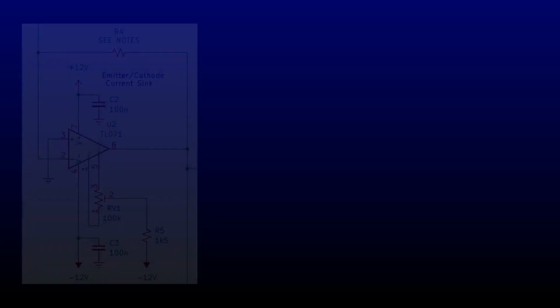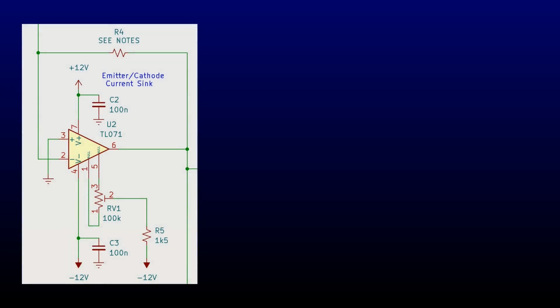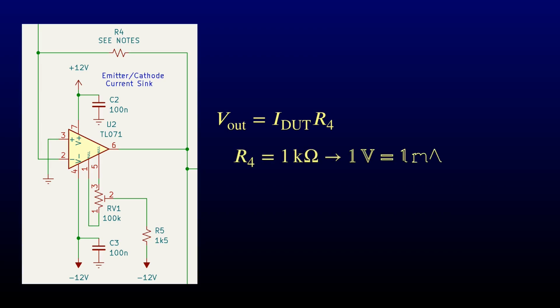In the initial design, I made the current measuring circuit look like this. For R4, I put a collection of resistors side by side on the breadboard, with values 1K, 10K, 100K, 1 meg, and 10 meg. Those let me select the scale for reading out the current as a voltage. If I assume a 10-volt full-scale output signal, I get full-scale ranges from 1 microamp to 10 milliamps.